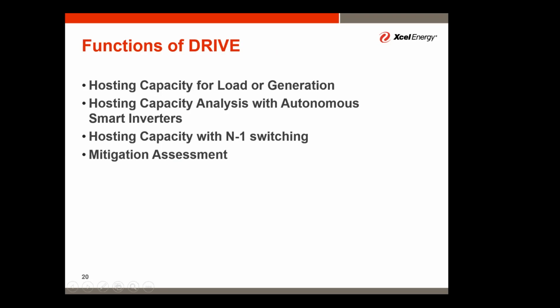I will also mention, as I said earlier, just wanting to provide a list of some of the additional functions within Drive. As we've already talked about, one of the main functions is hosting capacity for generation, but hosting capacity for load can also be performed. An added feature has been hosting capacity analysis with autonomous smart inverters, as well as N-1 switching conditions and mitigation assessment. Any questions on these additional functions?